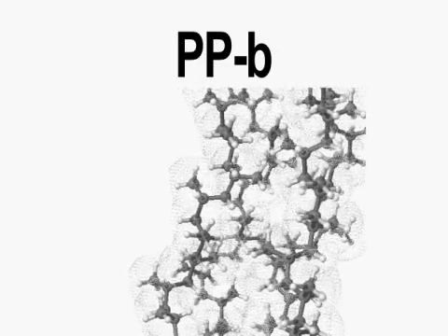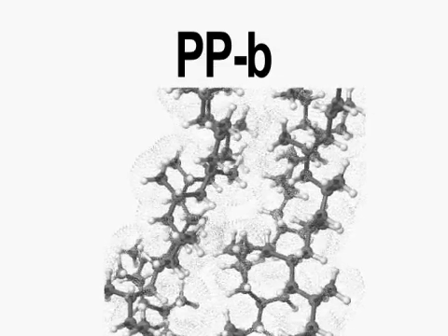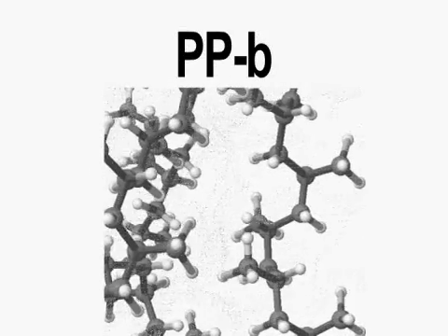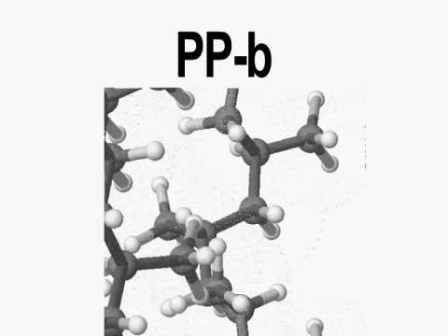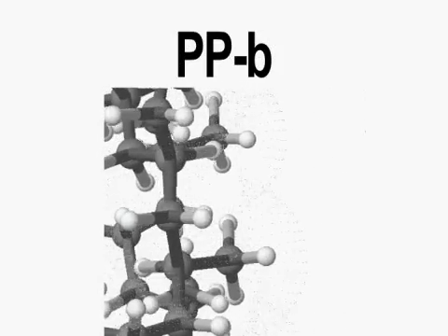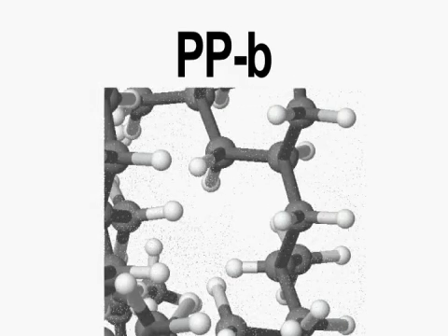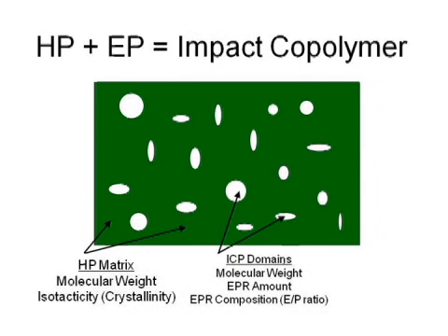With over 20 years of history in sewer and drainage applications, this is a highly crystalline material, offering a good balance of high resistance to stress cracking, high tensile and compressive strength, and good impact resistance. As I stated earlier, it is a copolymer, but it's also further modified with impact modifiers. For an impact modified copolymer, there's a homopolymer in the crystalline region of polypropylene, and there is an ethylene propylene rubber. This is a non-cured soft-set rubber molecule that's set into the amorphous region where the rubber floats literally between the polypropylene crystals.